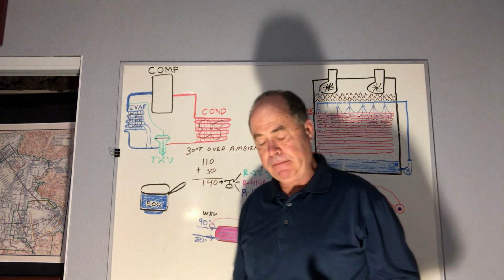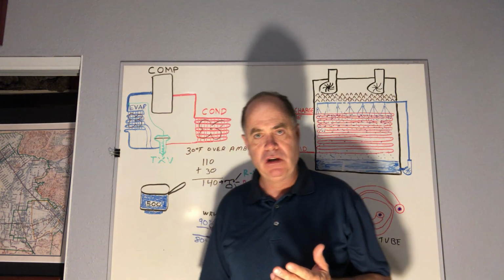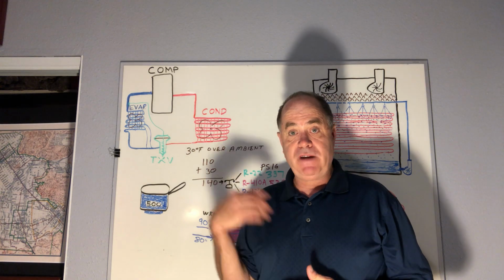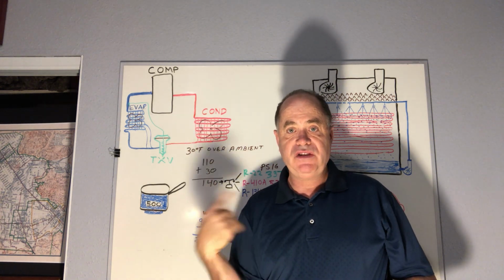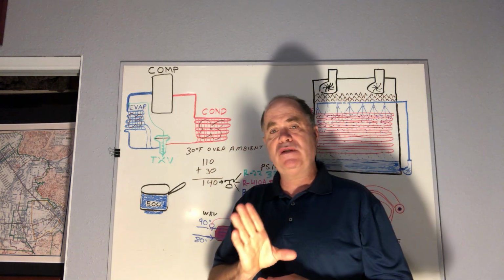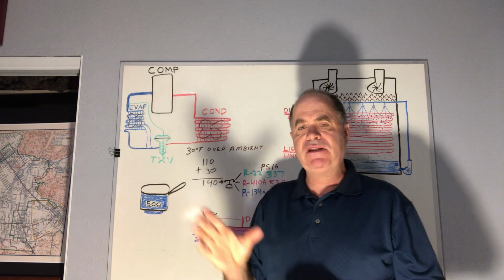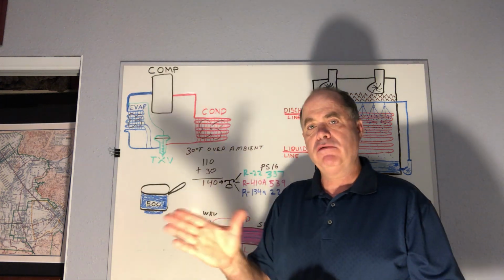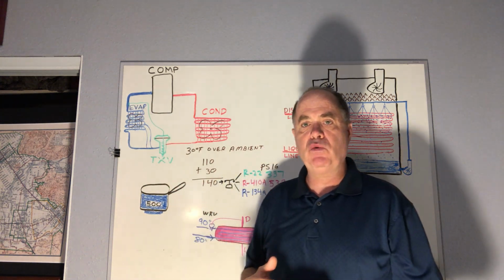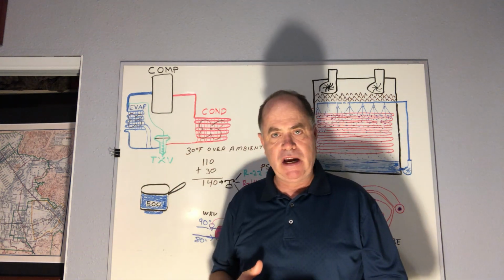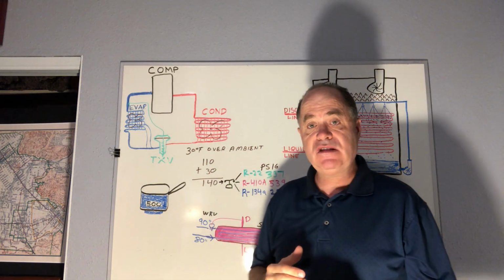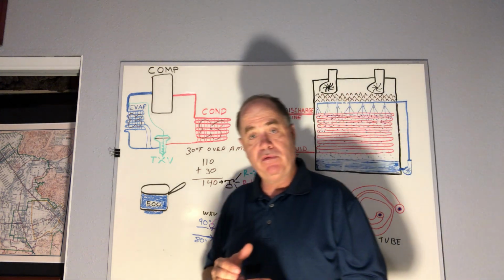The other ways that we can control head pressure with an air-cooled condenser is a variable frequency drive fan that speeds up or slows down with head pressure. Also, sometimes we'll have a certain type of bypass valve. It bypasses the condenser or a portion of the condenser, where the refrigerant goes around the condenser. That maintains a head pressure when the condenser is in a very cool environment. So we do have to have head pressure control when we're running systems, especially when it's not very warm outside.